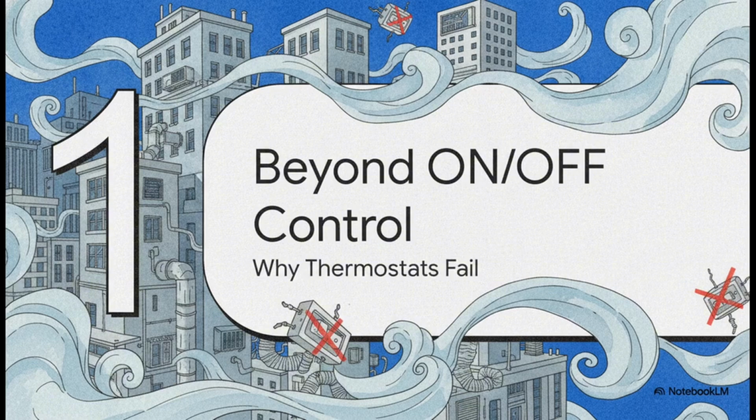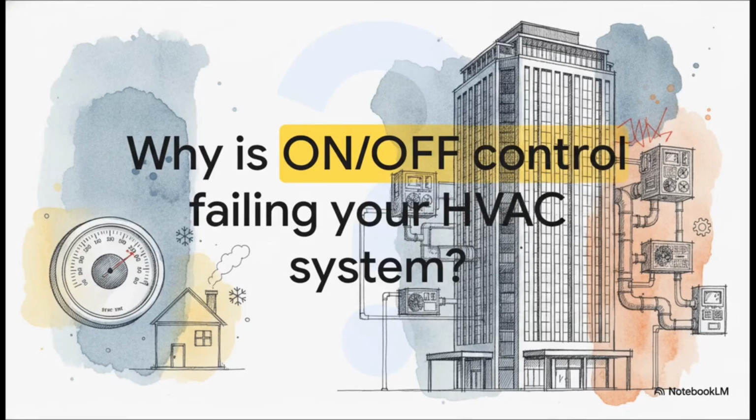Beyond simple on and off control, or why basic thermostats fail. So you might be wondering, why exactly is basic on-off control completely failing your HVAC system? Well, in a small residential setup, a basic thermostat that clicks on when it's cold and clicks off when it's warm, sure, that works absolutely fine. But when you scale that up to a massive commercial building with hundreds of zones, intricate air handling units, and giant chillers, that binary approach is literally a recipe for disaster. It leads to massive energy waste, rapid wear and tear on your expensive equipment, and honestly, just terrible occupant comfort.